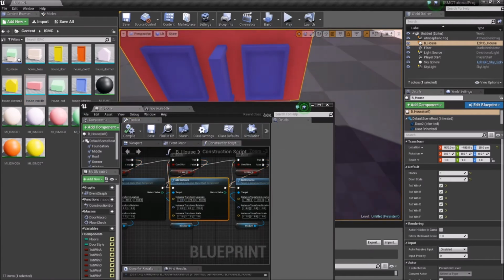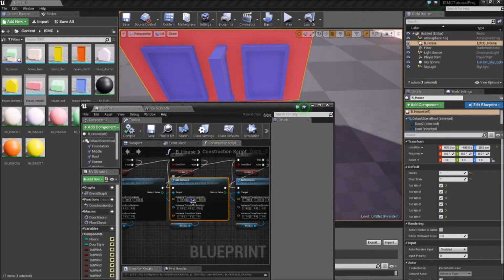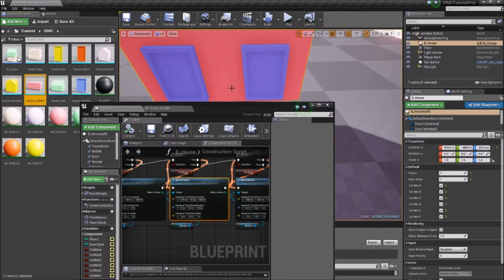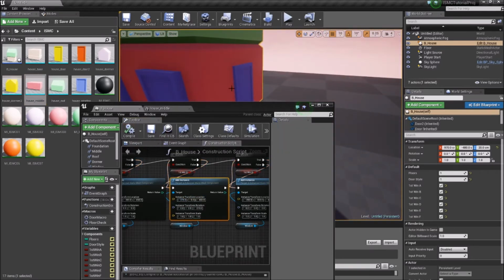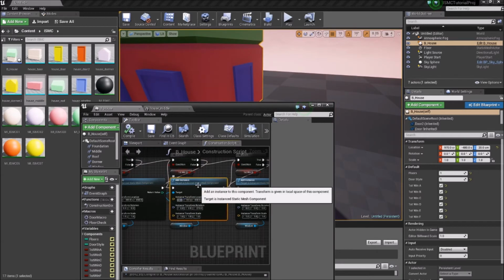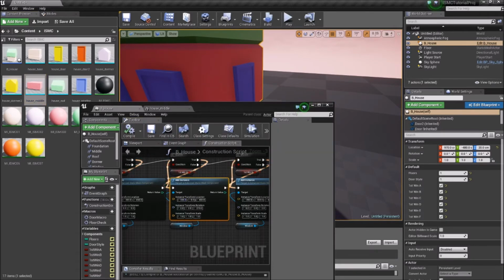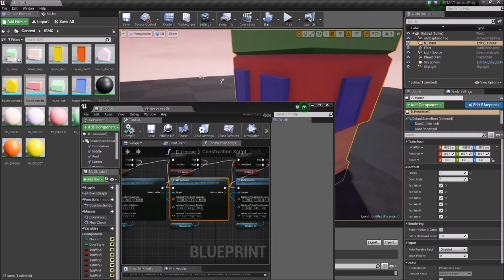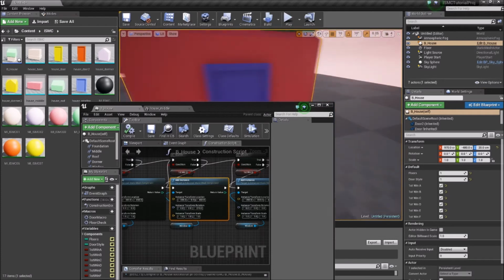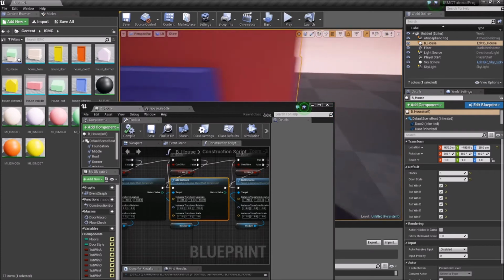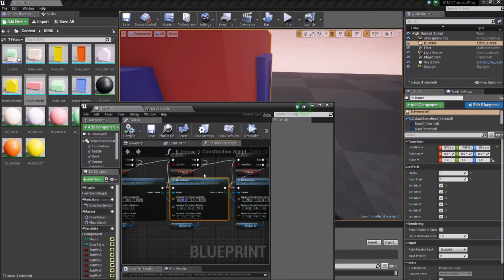That is not correct. So an offset of 0 in Y and 375 in X rather. Okay, so we want to get it sticking out just a little bit more so that it looks like the ones on the sides. And a lot of the setup for a blueprint like this is going to be just making sure all of your stuff is aligned the way that you want it so that it looks correct in your world space.